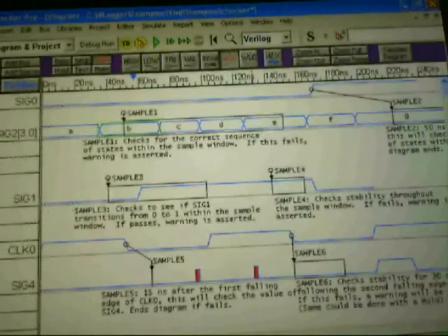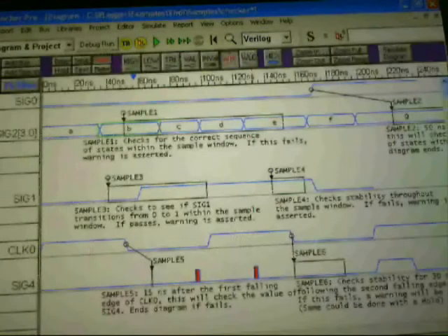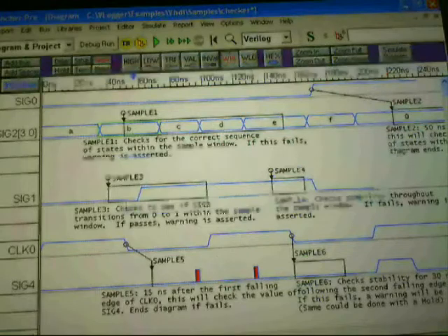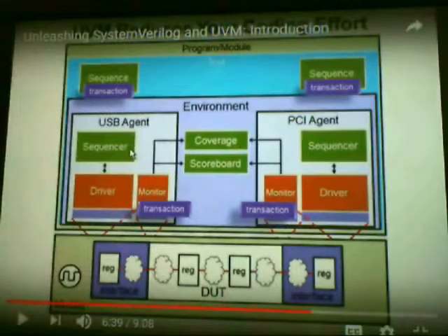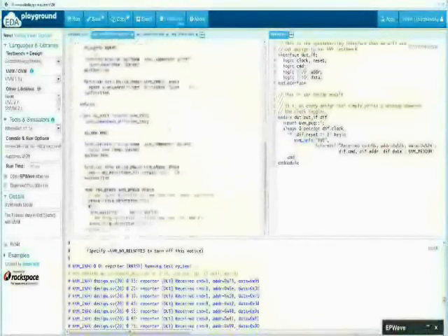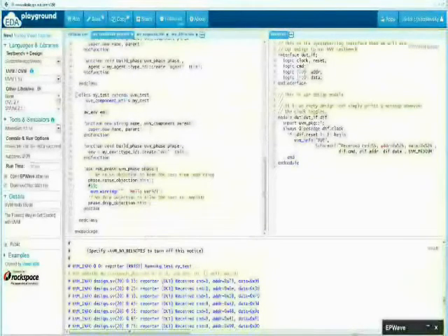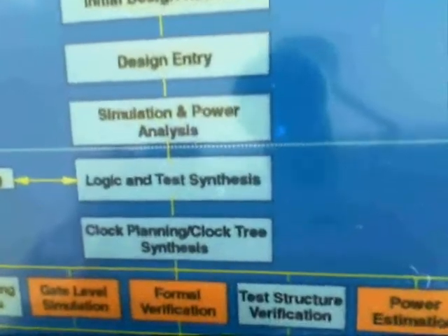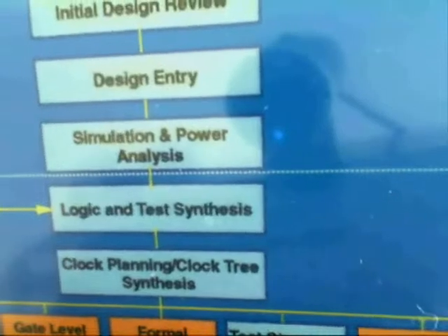Follow the design of an I/O system. 1. List the different types of I/O devices to be connected to the machine and list the standard buses that the CPU will support. 2. List the physical requirements for each I/O device. This includes volume, power, connectors, bus slots, and expansion. 3. List the cost of each I/O device, including the portion of cost of any controller needed for the CPU.